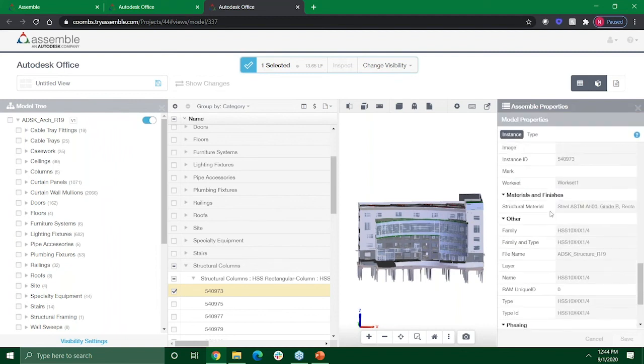And I need things by materials. I need things by cost code. I don't care if something's a structural column. That column could be one of 10 different materials or types or codes. But if you dig into the parameters, you'll actually notice that we have those things and those pieces of data actually living in the background. And this is where things get really useful, is the ability to take these parameters and use them as methods of grouping, sorting, and filtering.